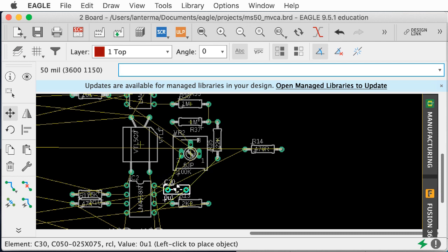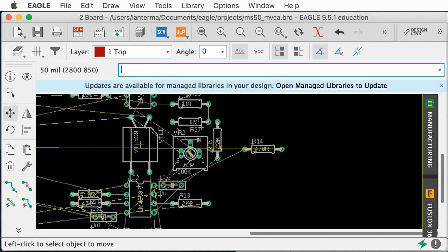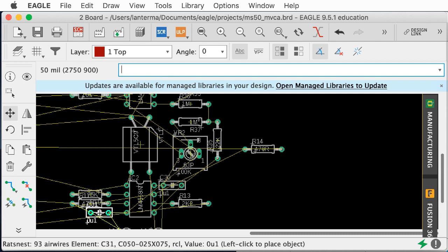Yeah, why not? Maybe I'll pull the resistors in later or have to pull these back. I don't think I'll need to, though. Move C31, so we'll use this to bypass the negative supply over here. Turn, turn, turn. Because we would like to get those as close to the chip as possible.